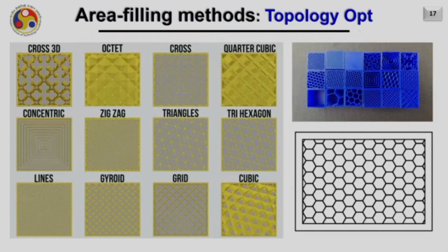However, in some cases, we really do not want 100% inside area filling. Means we need some hollowness inside, or we need to deposit less material inside, and hence we can save the material as well as we can save time. To deposit the material with less density in the inside contours, the strategies are slightly different.